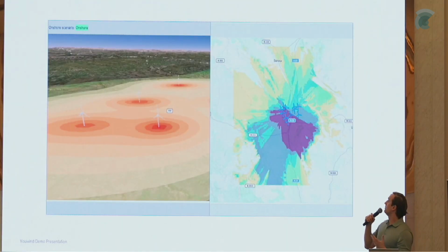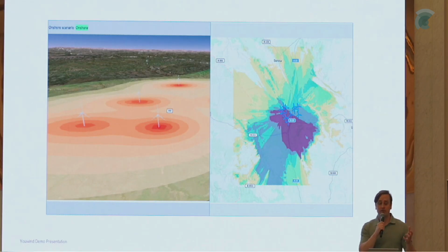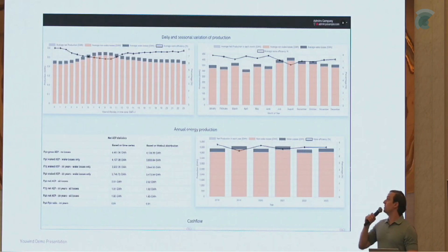And of course, for onshore, we need to evaluate this with the environmental impact. So what is the noise level of my turbines? What is the visual impact? Is there a shadow flickering? And what are other restrictions I might have? Where are the roads connected? And where's the grid as well? All these items come into play.